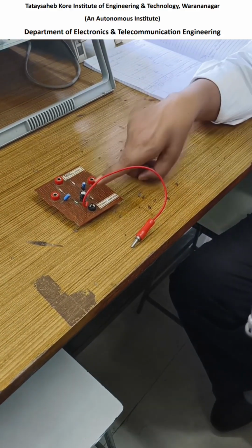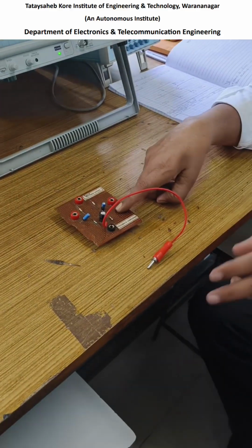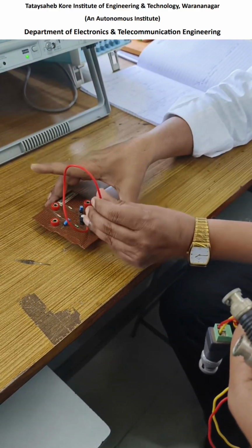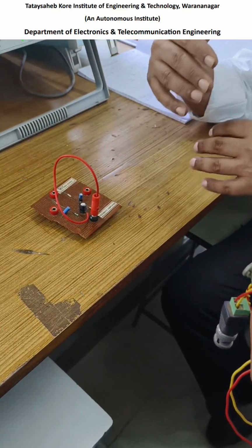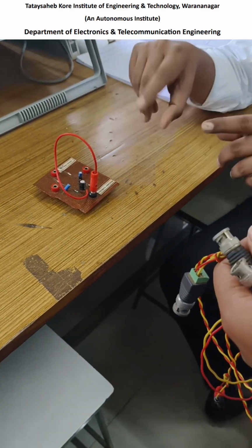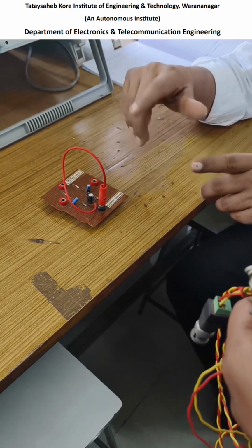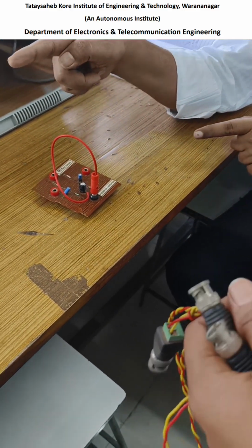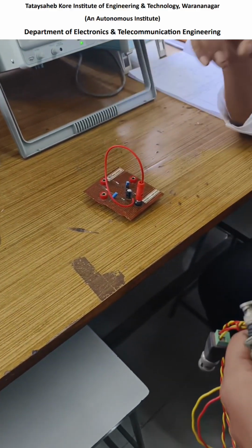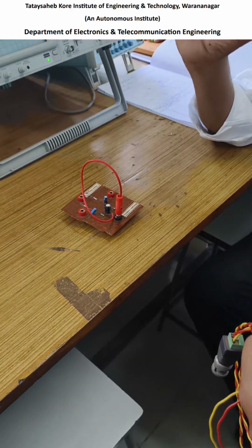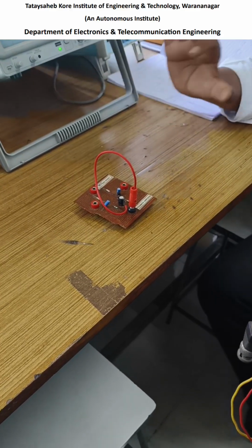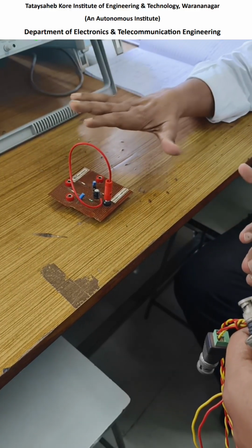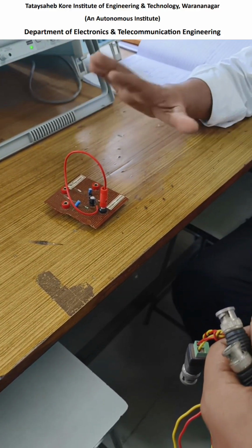So in this experiment, we have to repeat the experiment twice. Once, you remove this and take the reading. Second, you connect it and then take the reading. So you have to get the readings twice, once with CE connected and once with CE not connected. Take care that whatever input you connect from the signal generator to the circuit, the signal magnitude should be 20 millivolt constant for all the readings. You will not change the voltage for any reading, whether CE is connected or not. This 20 millivolt signal will remain constant.